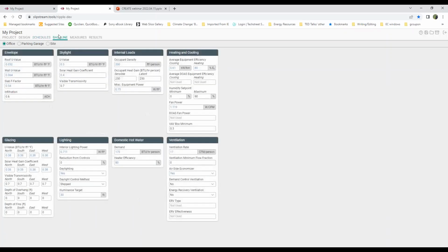With that, we pretty much have the baseline model all set. Like Macy pointed out, once we have a baseline model, that's just a code compliant building. So we're not going to change much of the baseline input. This is really telling the model what's the legally allowed building that can be built. Anything lower than this is technically not legally possible, although that does happen, unfortunately.